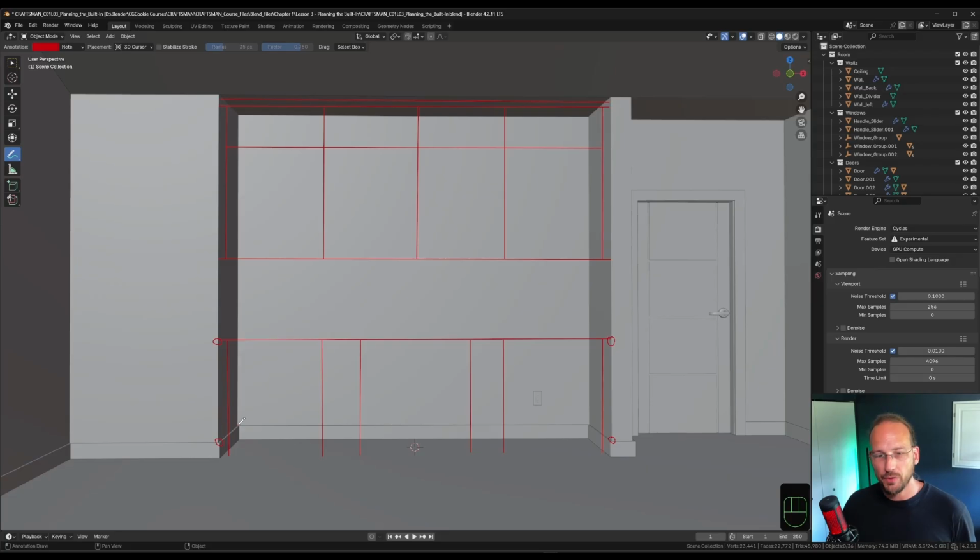And the same on the back side. Again, 90 degree angles are not all too common. So we want to take those measurements on the front and the back. And then if we see it's really, really crazy, then eventually we have to take one in the middle too. But in that case, there would be other problems in the whole building if it was that extreme. That's why we plan those trim panels with a little bit of width.